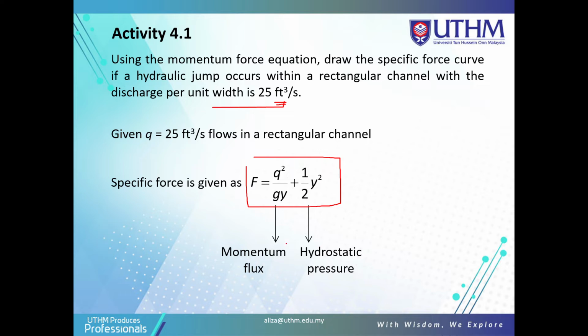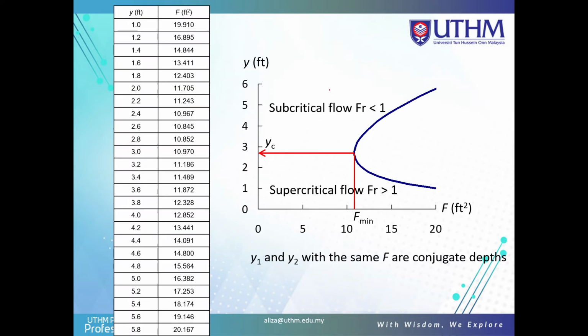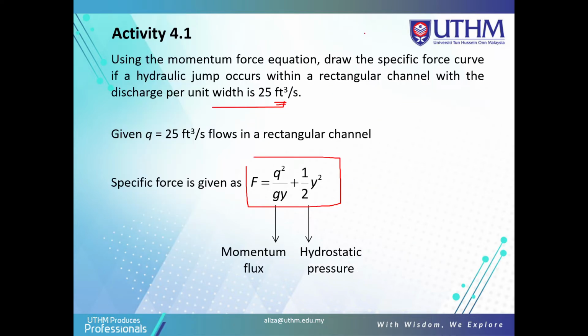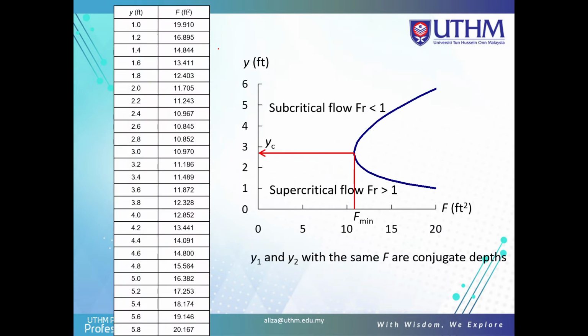We have learned the momentum and hydrostatic pressure in fluid mechanics, so now we apply that formula in hydraulics. Actually this is for using the momentum force equation: draw the specific force curve if the hydraulic jump occurs. Using this formula, you must take the y in the column and find the F based on the value of it. After this class, you try to do this